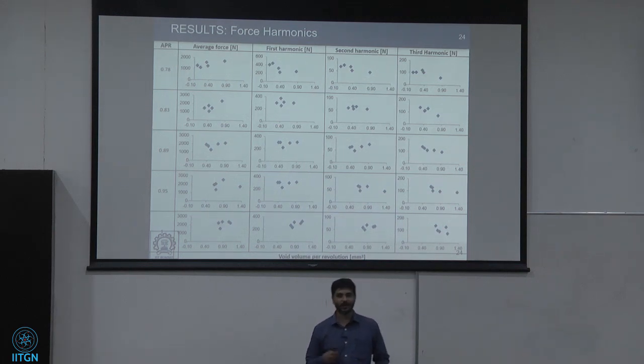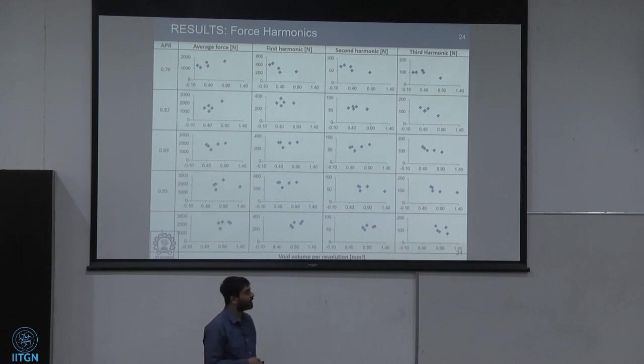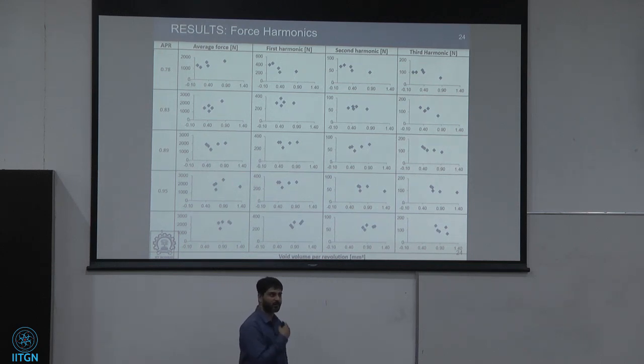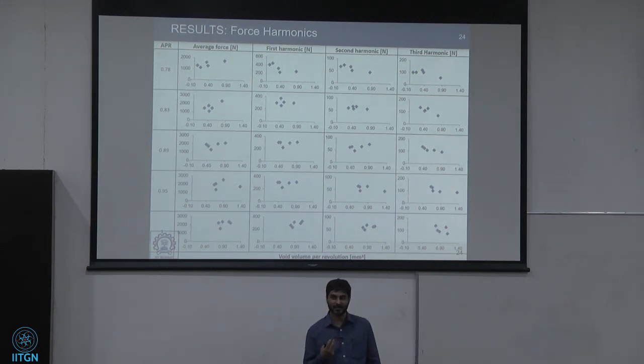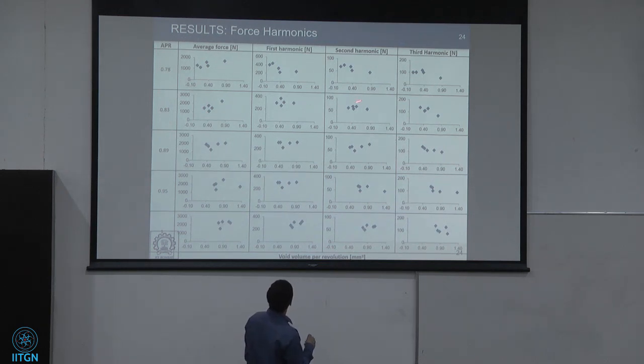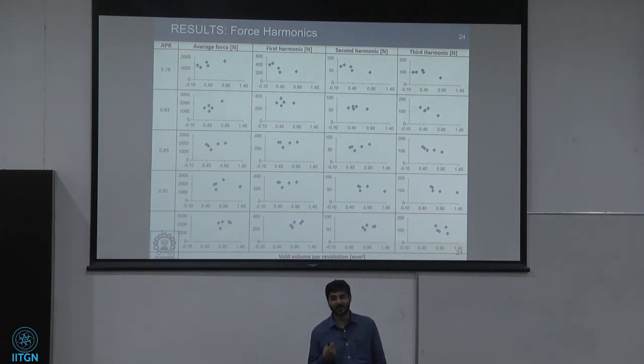Now one interesting thing: I was expecting to see some sort of strong trend in the third harmonic, because all of these welds were performed with a 3-flat tool, and I knew that there are defects formed in all of these. However, no strong trend is seen. The magnitude is pretty high. However, if you look at the second harmonic, the magnitudes here are at least twice the size of the second harmonic for any given case. However, I don't see the trend I was looking for.